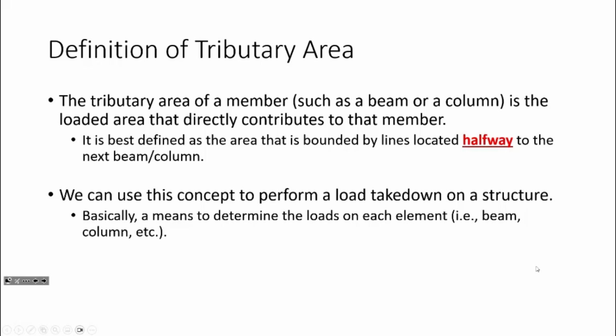And then once we get over here, that one's going to be responsible, right? So this beam is responsible for all the floor that's halfway over to this beam and then halfway over to this beam, okay? Now, I'm making some assumptions of one-way behavior, and I'll talk about that a little bit later, but for the most part, that's a pretty safe assumption.